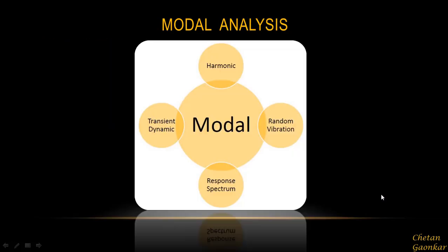So when we say modal analysis, basically this modal analysis is the first step for something called dynamic analysis. All right, so modal analysis is the first step to perform the dynamic analysis. Basically this modal analysis will give us how the structure behaves on its own. It will try to give us some inherent properties of any structure. So that is why the modal analysis is the first step of dynamic analysis.